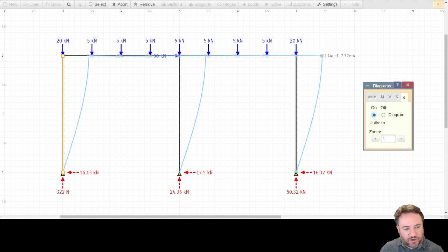So that would not fit an NBCC deflection limit. I would have to beef up my columns if these were my loads, if I wanted to meet the deflection limit, which was an optional part of our assignment. That's basically it. I'm able to get my moments and my shears and show my deflections. You'll notice that since the beam is much stiffer than the columns, we don't get much bending in the beam. There is some bending, certainly, but relative to the columns it's not very much. So probably what I want to do is beef up my columns.